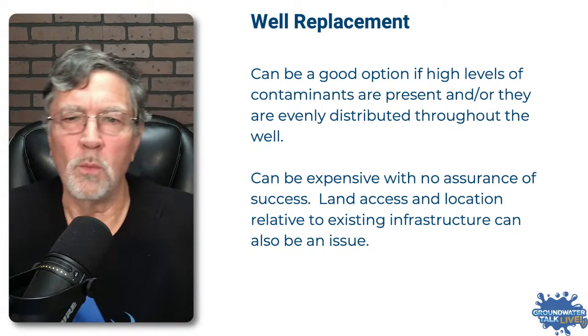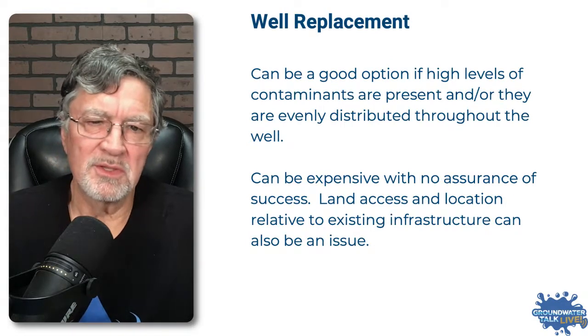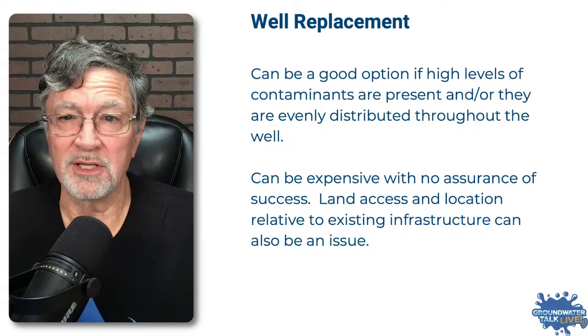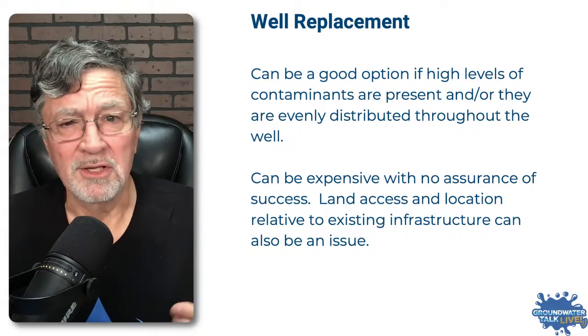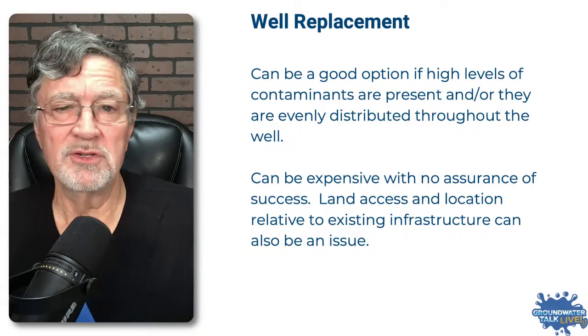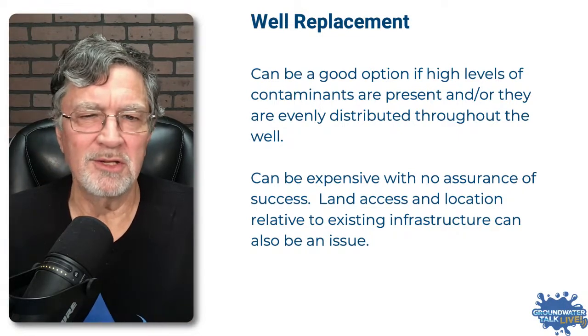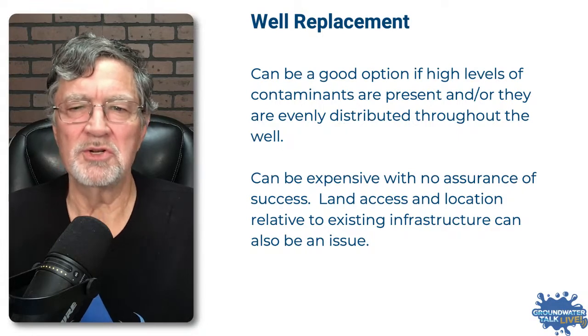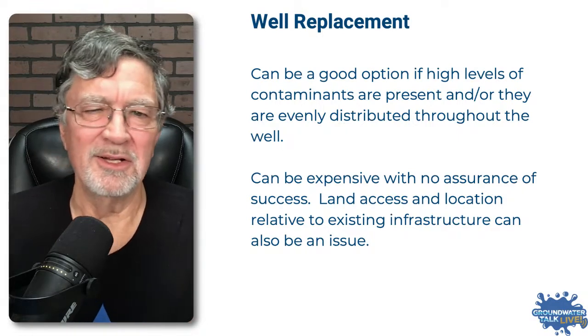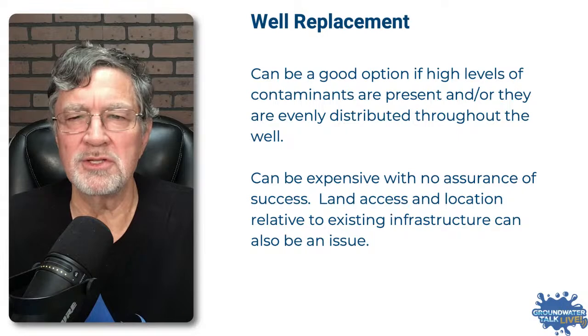So let's first talk about well replacement, because this is certainly a viable option. It can be a good option if you have high levels of contaminants that are going to be very expensive to treat, or if they're evenly distributed throughout the well, which doesn't make it a good candidate for well modification.